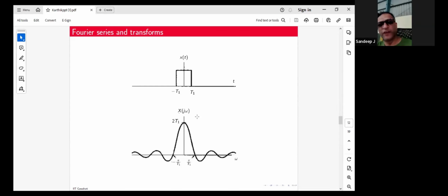For example, let's consider you have your fundamental at 0 dB and your second harmonic taken at minus 20 dB. Just as an example, the third harmonic sits at about another 20 dB less, like that. It's like a curve going in a linear decay fashion. So what does it actually take to get to that point? And the reason I'm asking is that this is something observed mostly in valve preamplifiers or valve tubes, the small signal to medium signal tubes, with the triodes especially.